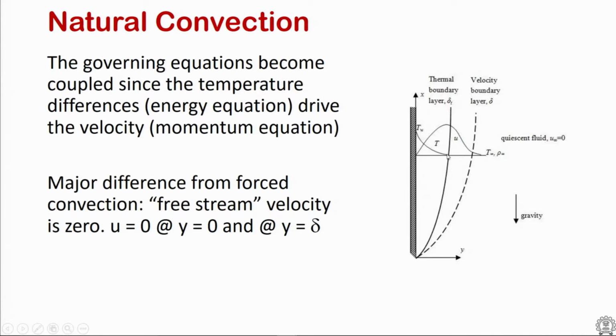This is a typical boundary layer in a Prandtl number greater than 1 situation, where the temperature boundary layer is here, while the velocity profile looks like this. Because the peak is happening here, this quiescent fluid is carried more and more by the maximum velocity, because of the shearing action of this higher velocity fluid on the quiet fluid sitting next to it. As that shear eventually dies down, you go to zero velocity. So this velocity profile will keep expanding as long as the plate length is increasing. That is the key to this.